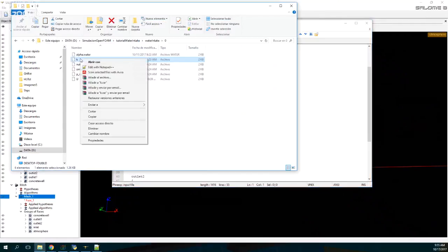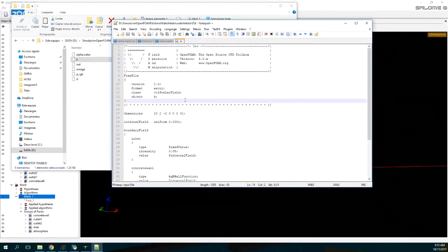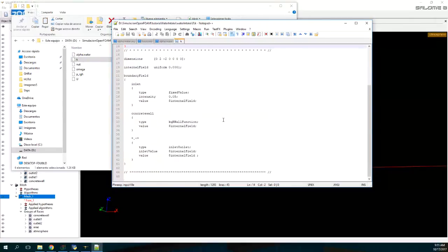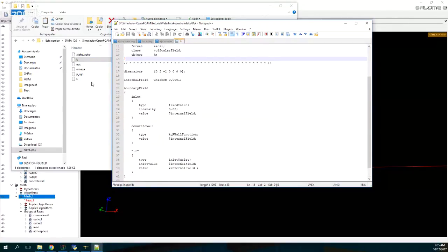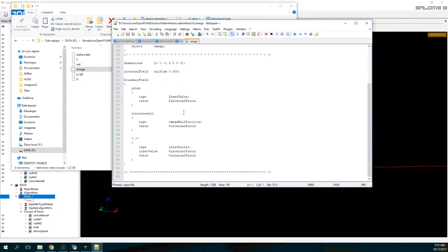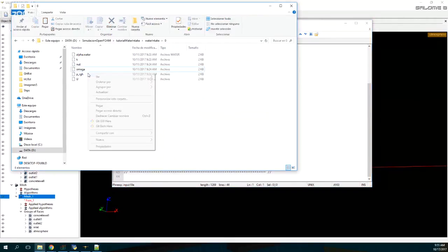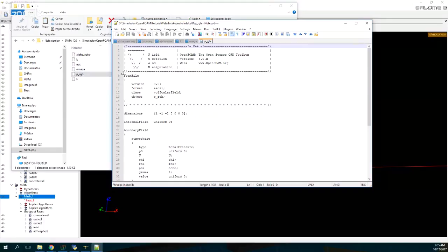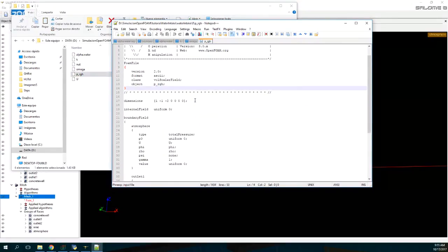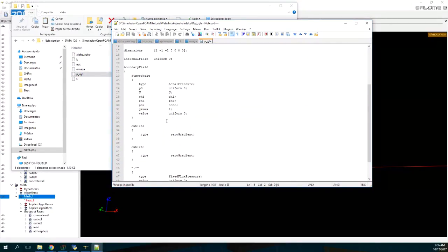Okay, great. So we have some values for the turbulence because this is OpenFOAM with a RANS model, so it's actually a turbulent model. So then you will see some values that define the turbulence. Okay, so it's the k and the omega. I strongly recommend that you go through the tutorials and the documentation, and see what k actually stands for and what omega actually stands for. Then we go to pressure, and see the atmosphere has these configurations.